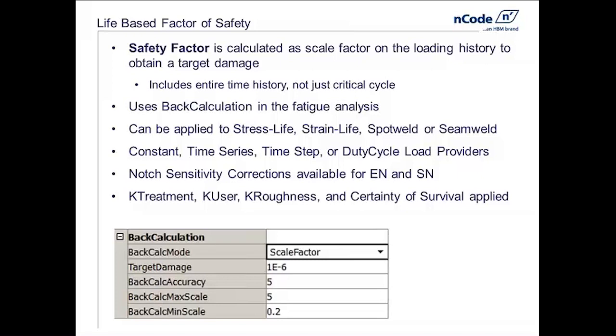obtain a target damage. So I'm actually doing a fatigue calculation here, and I specify a given target damage that I want to hit, and it will calculate for every node in the model a scale factor for the applied loads that would give me that target damage. It uses a facility inside the solvers that's called back calculation.